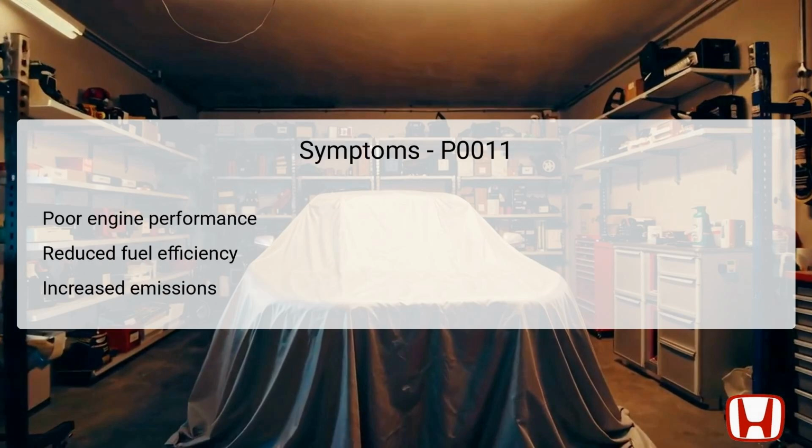When the DTC P0011 is triggered, several symptoms can manifest in the vehicle's performance. Owners may experience poor engine performance, characterized by rough idling or a noticeable reduction in acceleration. This is due to the incorrect timing of the intake camshaft, affecting the engine's ability to operate efficiently. Moreover, fuel efficiency may decline as the engine struggles to maintain optimal combustion conditions under varying loads.